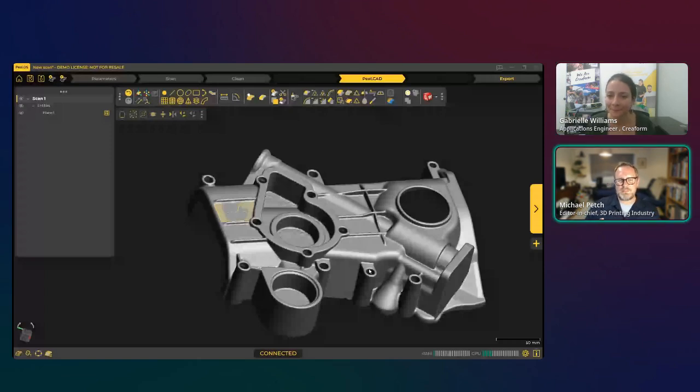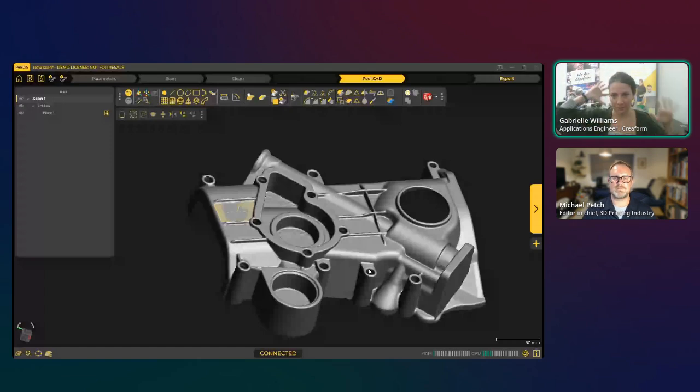Do you have any particular tips or tricks from your experience that you can share with people? Oh, yes. Okay, here's one. If you're scanning a person, which I feel like a lot of people here might want to do when they first get their hands on a 3D scanner, I recommend, because I gave a training yesterday so it's fresh in my mind, scanning the face first, and then maybe getting under the chin and so on, and then going around and doing the rest of the head.